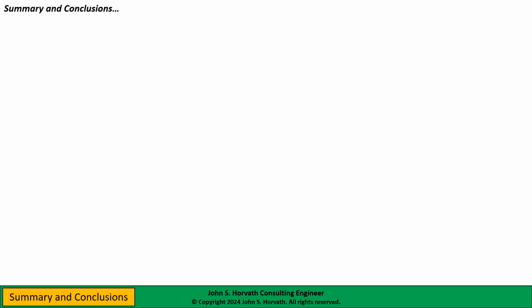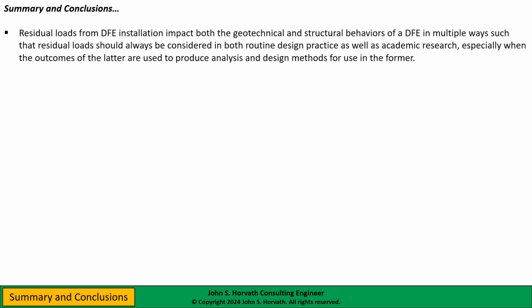So to summarize and conclude this presentation, residual loads from DFE installation impact both the geotechnical and structural behaviors of a DFE in multiple ways, such that residual loads should always be considered in both routine design practice as well as academic research, especially when the results of academia are used to produce analysis and design methods in design practice, which is typically the case.